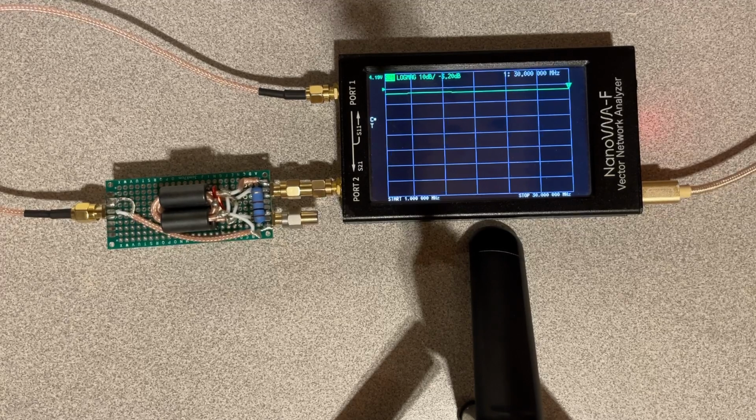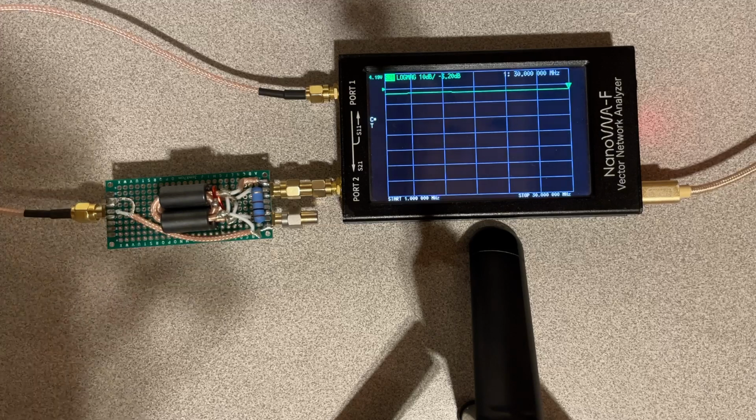All right, so now I'm back. Before we begin, I just want to clarify one point. Earlier in the video, I kept saying center tapped, and actually the 4-to-1 transformer, which had 2 turns and 2 turns, is technically center tapped. And for the 2-to-1 transformer, we had 4 turns and 3 turns, so we just refer to that as a tap. Actually, auto transformers could have multiple taps, as some of you might already know.